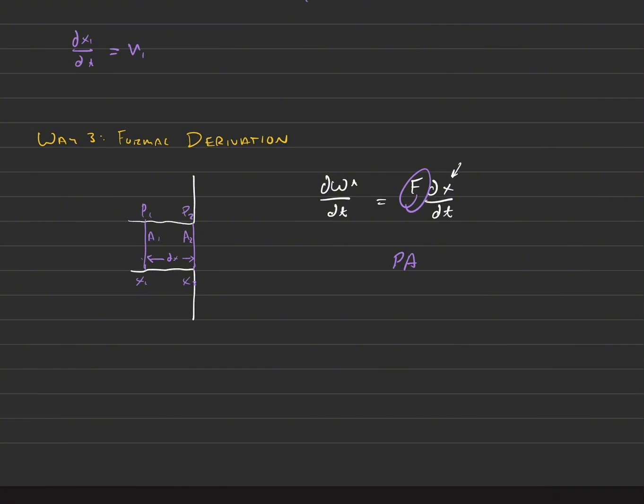We know that because, you probably haven't had fluid flow yet, but we know that dP over dx, at least in turbulent flow, is going to be equal to 2 times the Fanning friction factor, V squared, over D. And that's definitely not linear. Or it is linear, but it means the pressure does change.